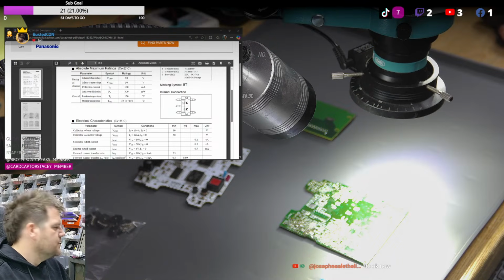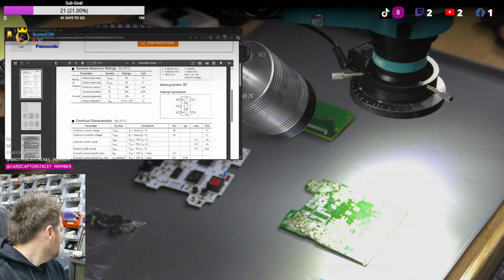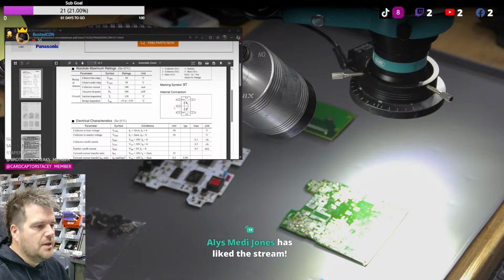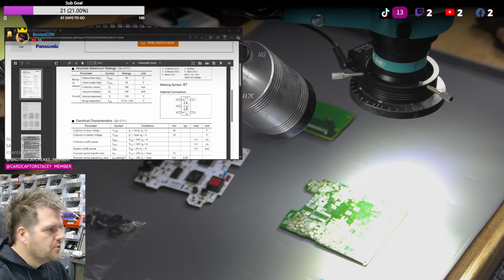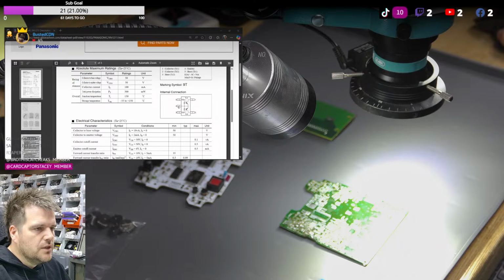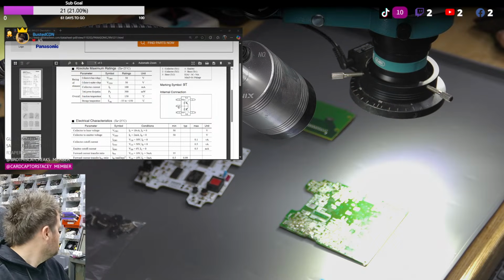So two NPN transistors with two separate bases, but the bases are already pulled high and also available on pin 4. So you can control both the center tap point and the bases. So typically for low voltage drop bi-directional switches, I'd say they'd use these for. I'd use this setup in a 2 MOSFET configuration for a 0 voltage drop setup.